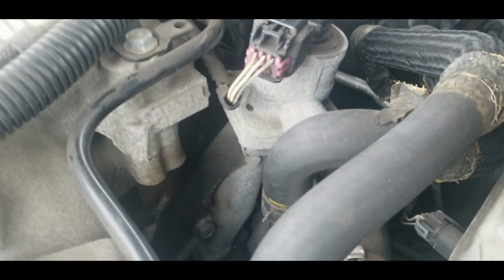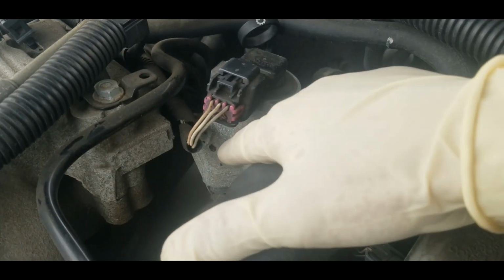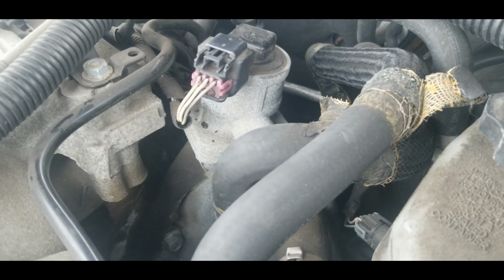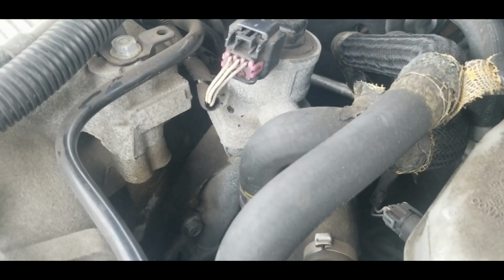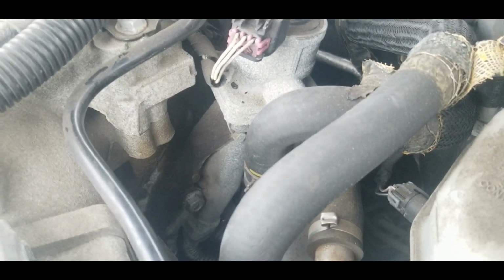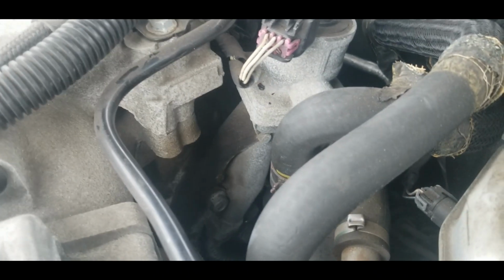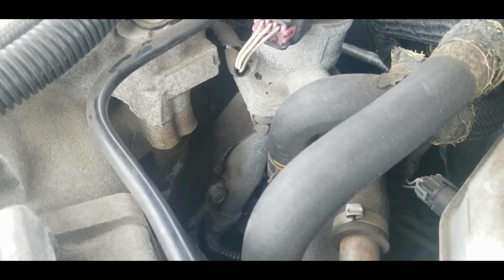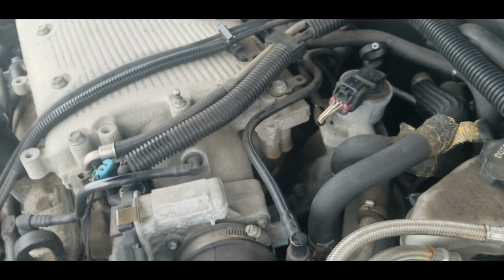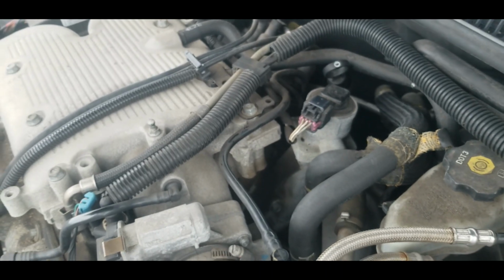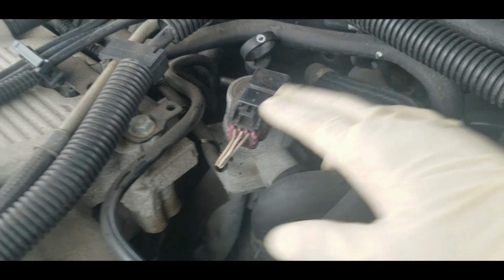What I'm thinking is, the channels where the air flows through have to be a certain size. So with the carbon buildup inside of those channels, it will decrease the diameter of the channel, which will increase the pressure in the system, because now we've got the same amount of air going through a smaller tube. That's one of the codes the computer is kicking, that the pressure is incorrect. Secondary, it's saying that this valve is stuck.